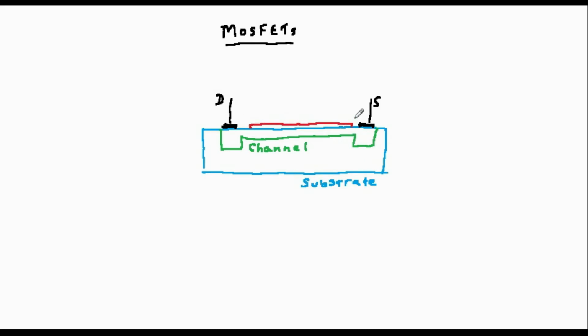On a standard silicon substrate, this insulator is usually silicon dioxide, SiO2, often made by heating the silicon in the presence of oxygen. We are most familiar with SiO2 in its non-crystalline form as glass. The simplicity with which a good insulator can be fabricated on silicon is one reason why it's such a fine material for making this type of electronics. On top of the insulator is deposited the metal gate electrode. There is no direct connection between the gate electrode and the main device material. They are separated by the silicon dioxide.